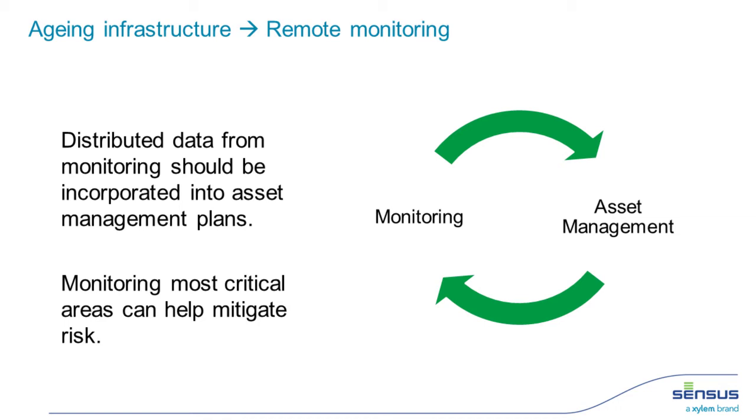Once they had the AMI system, they realized they could monitor the pressure on either side of the PRV to ensure that it was working, every few hours. This greatly increased their serviceability, because now, rather than having to wait potentially a month from when the PRV failed, they could know within a few hours. But they also didn't have to send the trucks around, so it saved costs as well.